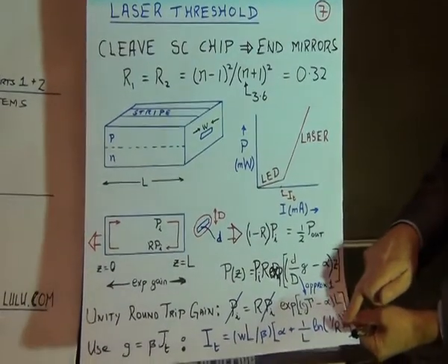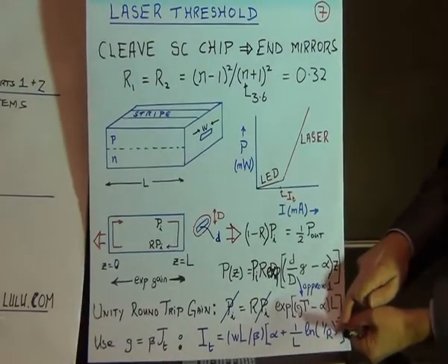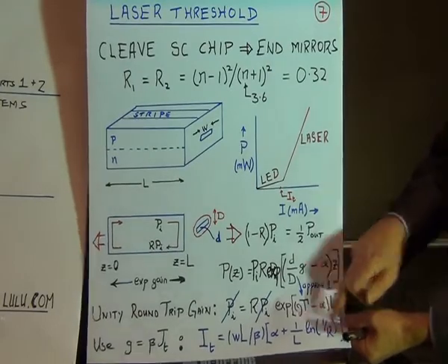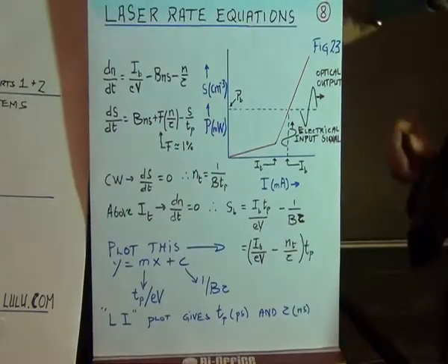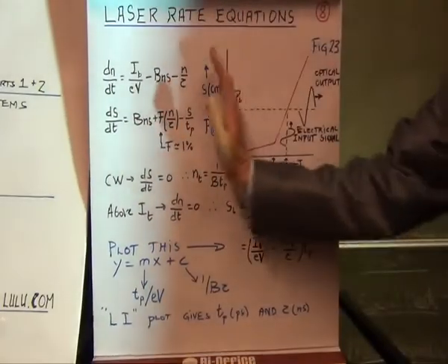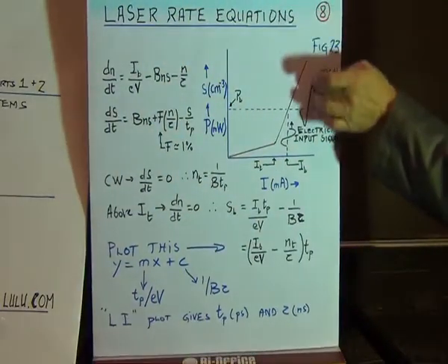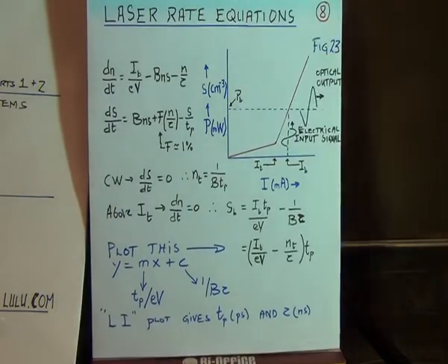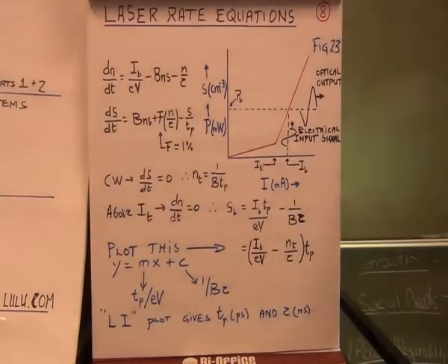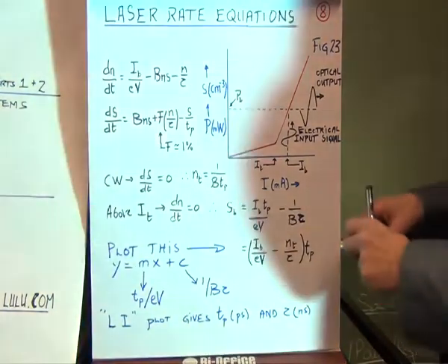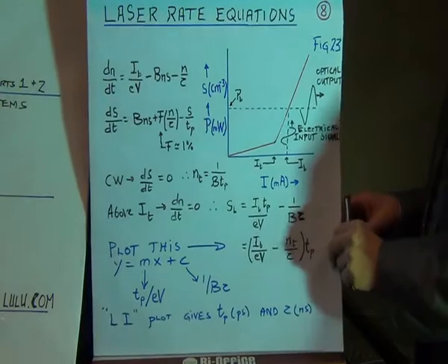Right? If you increase the reflectivity due to feedback from an optical fiber, the threshold goes down. And when the threshold goes down, the whole curve moves down, and you're modulating on a higher, different part, perhaps a non-linear part of the graph. So we must be very careful in these systems about back reflections of any kind.